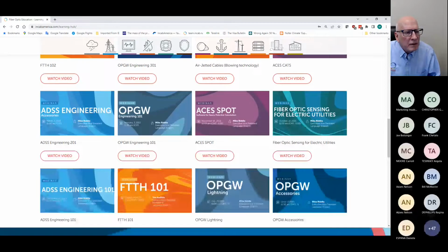Alexis has posted a link that you can get. What are typical lengths of the spun type of cable? So the wrap type of cable, I take it, is what you mean. What I understand is typically something like 6,000 feet has been common, whereas OPGW is regularly installed at 20,000 feet and more.